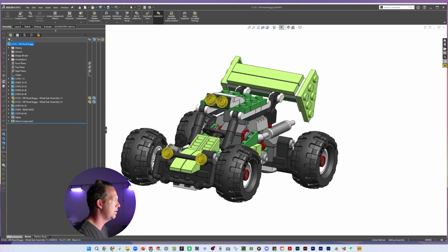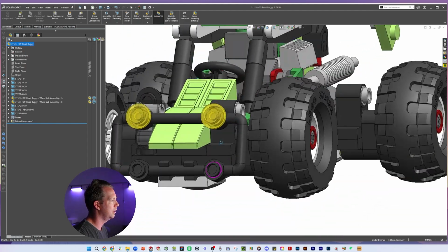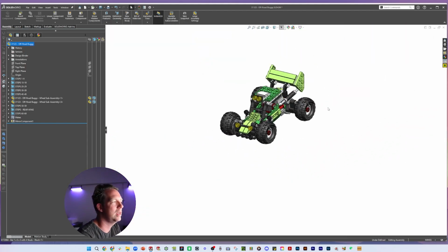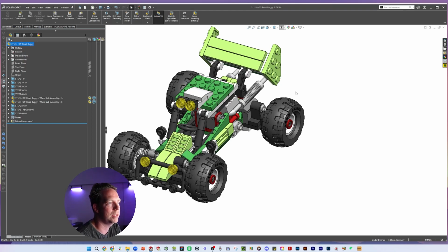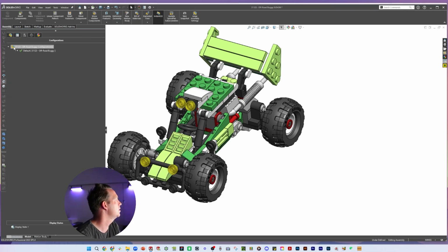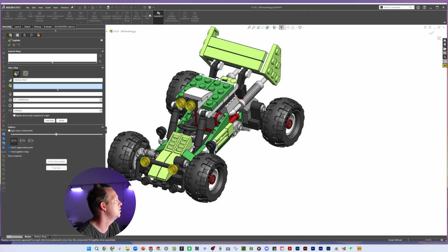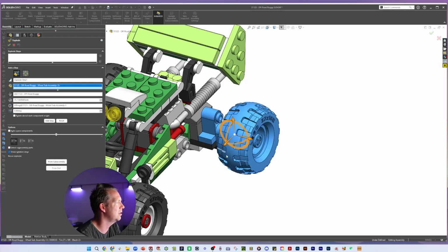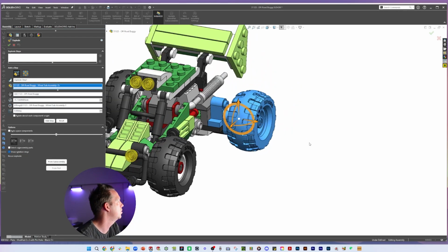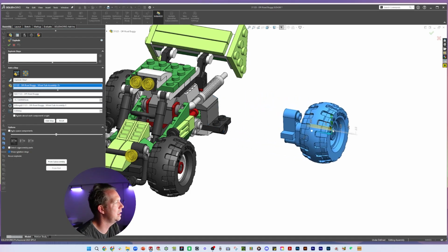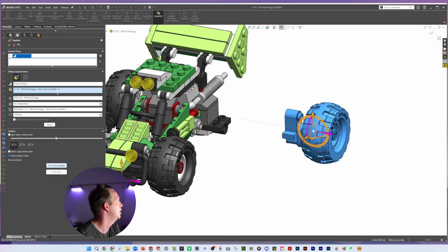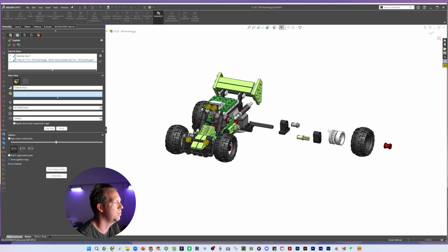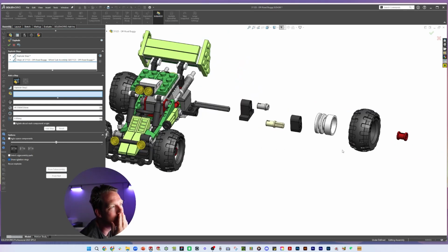But very first, here's the other complicated part. Like what we just did for the wheel, I'll show you now how that interacts within this general assembly. So there's no exploded views here currently. If I press exploded view, I have the option, down here, of this tick box that says select subassembly parts. If I uncheck that and I select a subassembly, it's selecting the whole thing, right? And I could drag that out like this, and then press from subassembly. I'm just going to explode that, but that's not how it was built. It's not how it's built in the instructions.